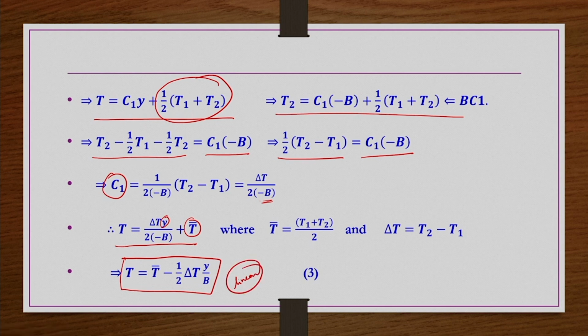Before solving the problem, from the problem schematic we do not have any information whether it is linear or non-linear. So now, by simplifying the energy equation and applying the boundary conditions, we understand the temperature is a linear function of y. Fine. So the temperature distribution is known.